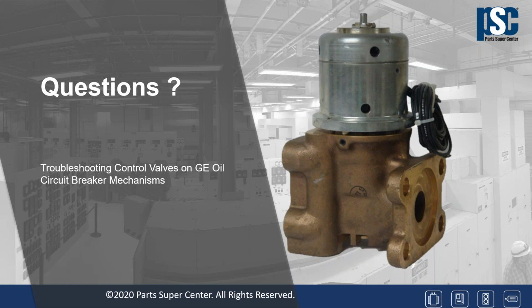We will remanufacture your valve. We will take that back as a trade or as a core exchange and provide you with a valve with the same as a new valve warranty. So when we take those valves back, we will remachine the main seat. We will hydrostatically test the valve body. If it's leaking, we will impregnate it so that it no longer leaks if it's a porous casting, which does happen from time to time.